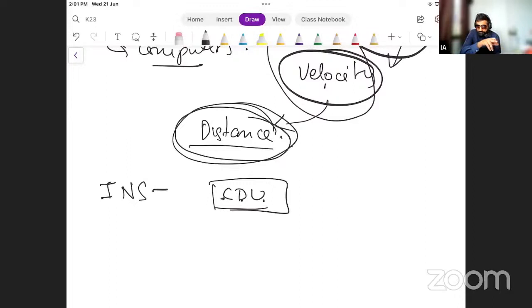Okay. So in the INS, you can feed in the present position accurately. Then that position is the reference position with which the INS will sense all its other data. The accelerometer will sense the deviations from the present position, calculating time and velocity, and of course the direction. When they figure out that we have flown for this time at this velocity from this position, the computers can determine the present latitude, longitude position of the aircraft automatically by itself. So that is the function of INS.